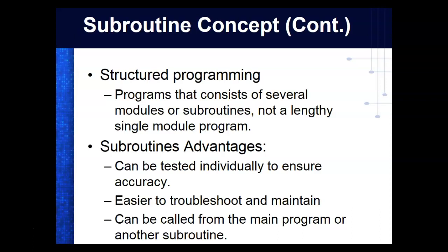So what we do is we break it up into individual little modules. Usually each module has its own dedicated function, and it makes it so much easier. So we can test programs, we can troubleshoot, we can maintain. So this is called structured programming. It is when you take a long program and split it up into individual modules, what we refer to as subroutines.